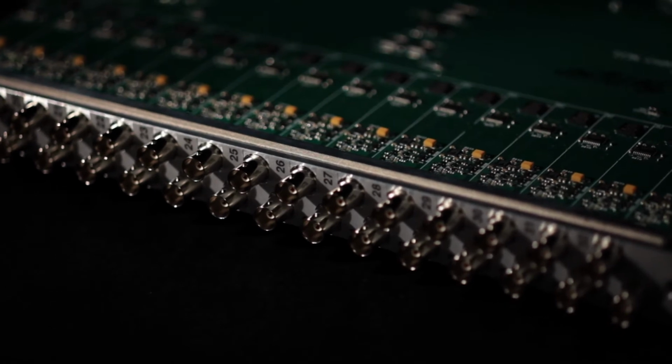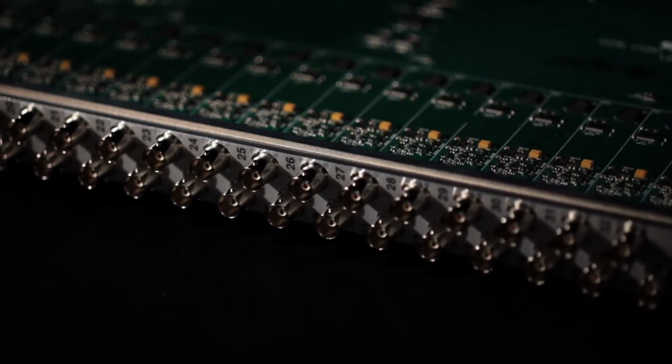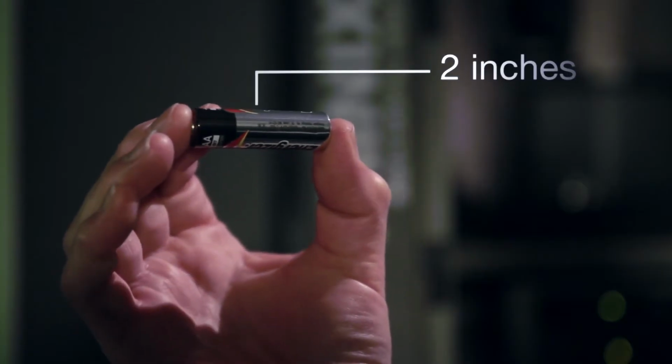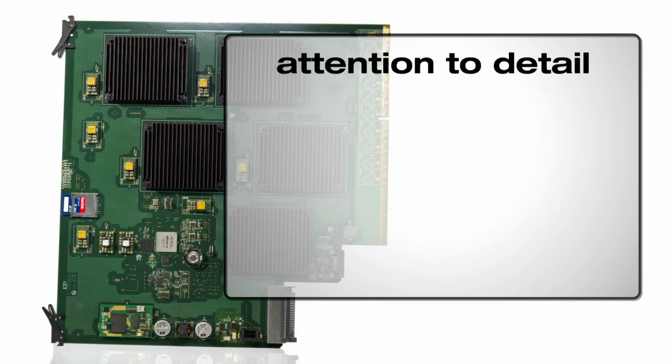At standard definition rates, a digital bit is about 1/2 meter long on a circuit board. At 3 gig, the length of one bit time is only 5 centimeters or about 2 inches long on the circuit board, the same size as this battery. This requires careful attention to detail for high quality signal integrity.